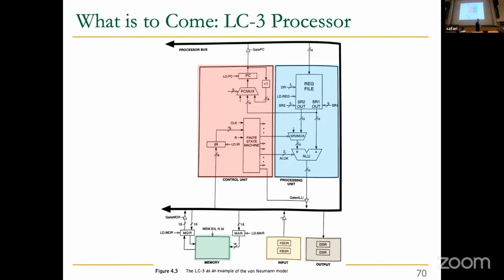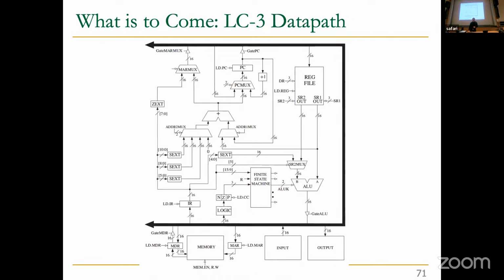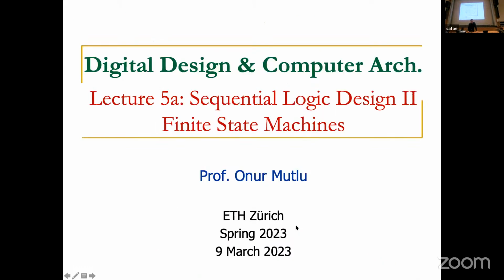We're going to design this LC3 processor that can process instructions from a small instruction set. And you're going to do something like that in your labs as well. And this is going to be the data path that we're going to see and build. You can see some of the elements that we've seen so far, multiplexers, for example. There's a decoder somewhere that's not shown over here. But we're going to use everything that we have used so far. You can actually see the tri-state buffers over here, right? And then there's a bus over here. And these tri-state buffers control what data value gets loaded onto the bus. Again, that's a teaser. We're not going to go into that right now.